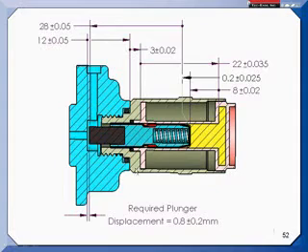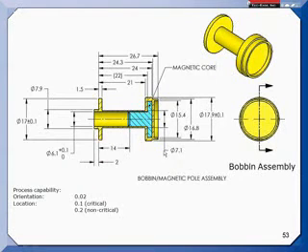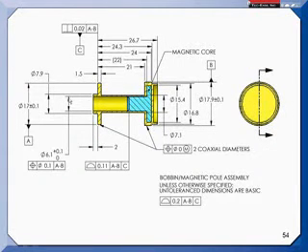And so I'll probably only make contact with one high point on this surface. So I called one of these features A, the other one B, and made A-B my primary datum feature for the bobbin. So this was B, this was A, and then I said A-B, and then this became datum feature C.